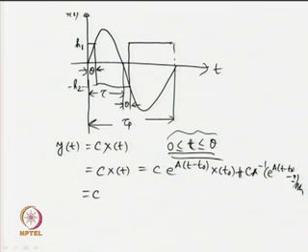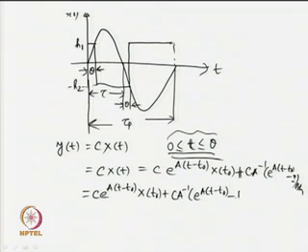The output signal will be given by the expression C e to the power A(t minus t0) x(t0) plus C A inverse e to the power A(t minus t0) minus I B h1, because the input to the system at that time is this piecewise constant input h1, for which we have got the output starting from time t equal to 0 till time t equal to theta. So, this part of the signal is given by this expression y(t).